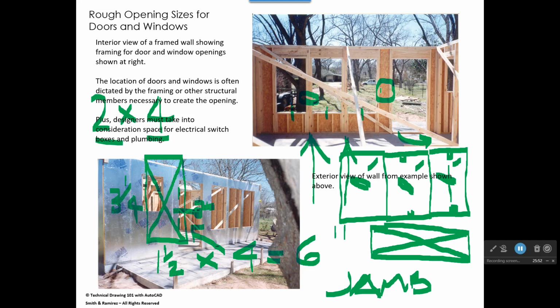If you don't have enough space between these studs right there, you're going to get a call from the electrician because you're showing 3 switches there. And if there's not enough space in there, they're going to give you this nasty phone call. And nothing makes electricians and framers happier than calling the designer and telling them they're an idiot. Okay? It just makes their day. So just beware of that.